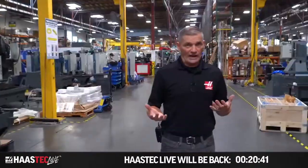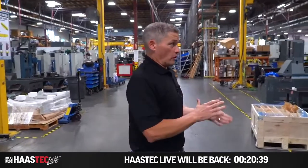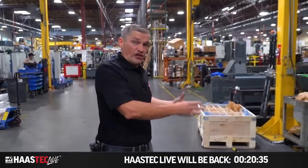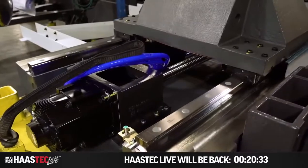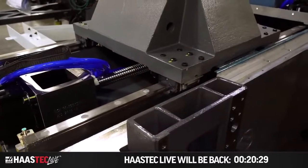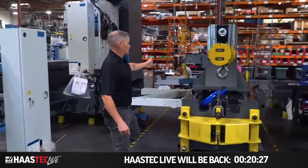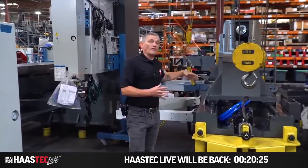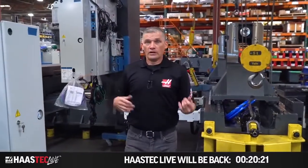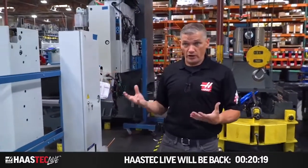It's what we call the stacked axis method. It's pretty simple, really. We start with the base on the ground, lay down the linear guides, then the saddle, then the table. Typically, we build the column offline separately. We'll put down the linear guides and ball screws there, and then we'll attach the spindle head to that, and then we'll lift that column assembly and put it onto the base. And there you've got your entire basic machine assembly ready to go.